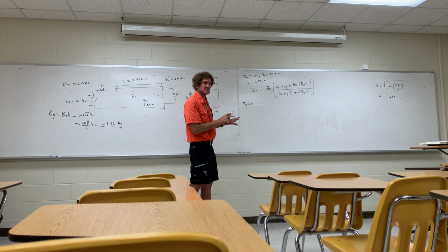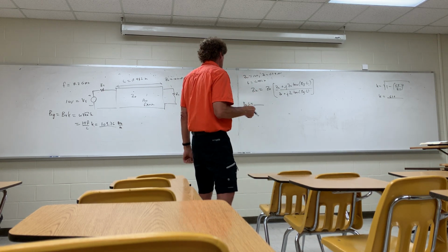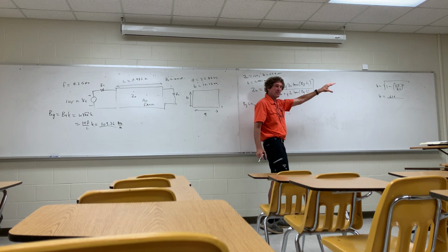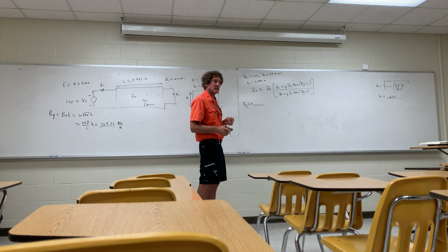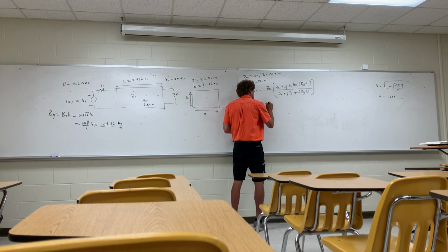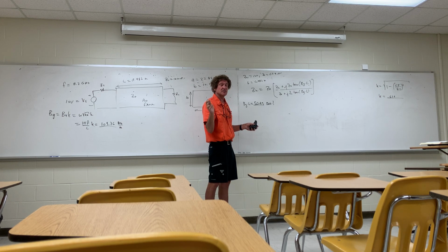I just wanna make sure we're consistent, that everybody sees this. It probably wouldn't be a bad idea to take the tangent of beta guide times L and put it in the memory, so you can just pull it back, but, anybody on that? 50.49. Remember, this is radians, not degrees, so when you do the tangent calculation, do the tangent calculations in the radian mode. Got me on that? But that's a mistake people will make. It's very easy, especially at 8 a.m., to not remember that the mode is critical there.